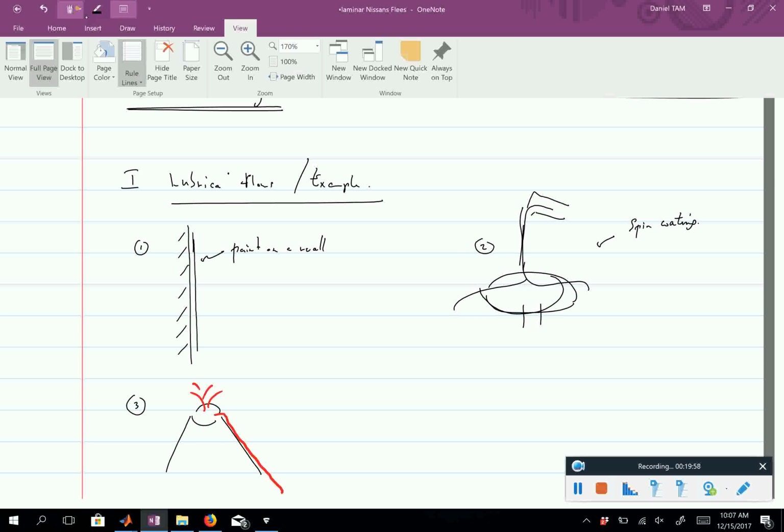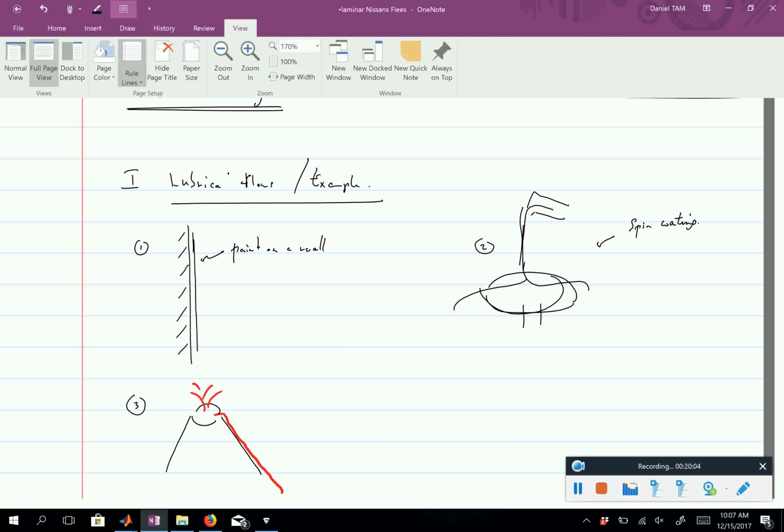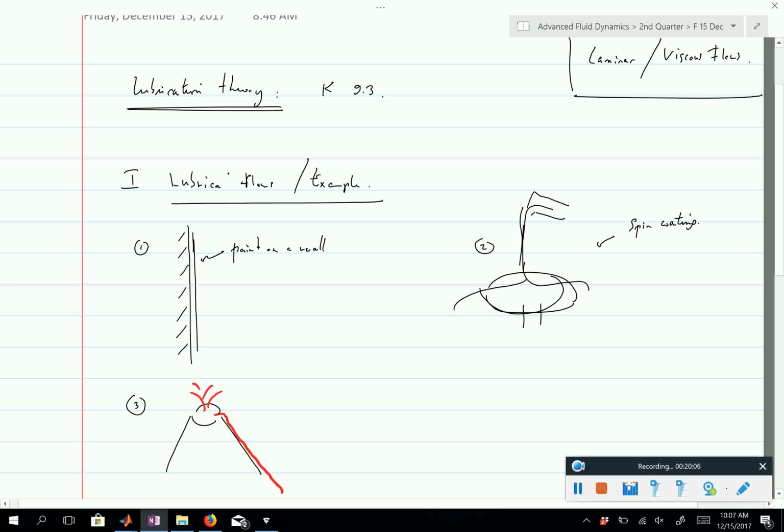Now there are certain cases, let me tell you directly, where the two length scales are very different, and it's not lubrication. So a river is not a lubrication problem, and you know that because if you're thinking about the flow of water in a river, the effects of inertia are very important. Those are the ones that dominate.